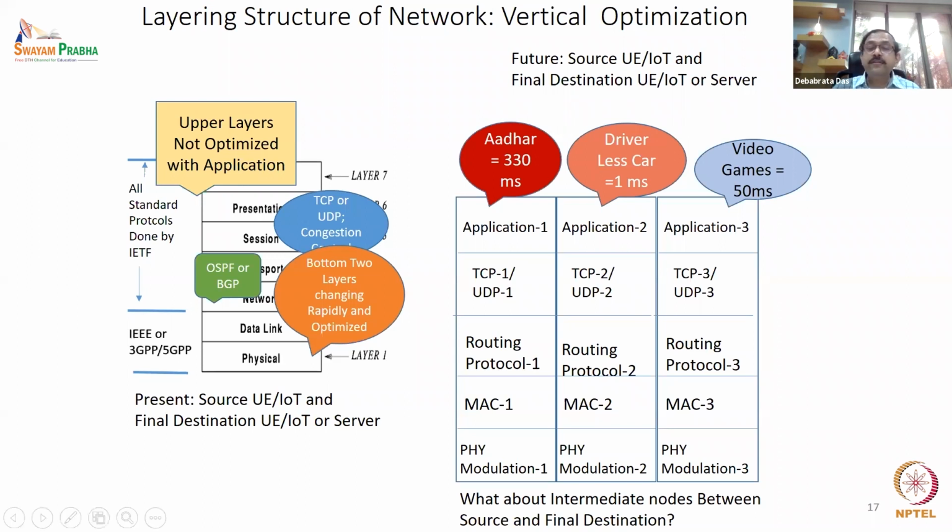Then the PHY, look at my mouse, this PHY will inform the MAC, change your scheduling algorithm. Don't send me packets so fast because the medium is bad. I'm pushing the packets, but they are not reaching the base station. But they have a constant exchange of control signaling about the medium. So the moment the PHY informs the MAC, they optimize the speed between MAC and PHY. Got my point? So this is called optimization between these two layers.